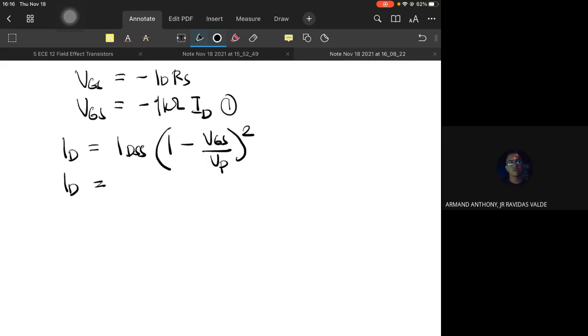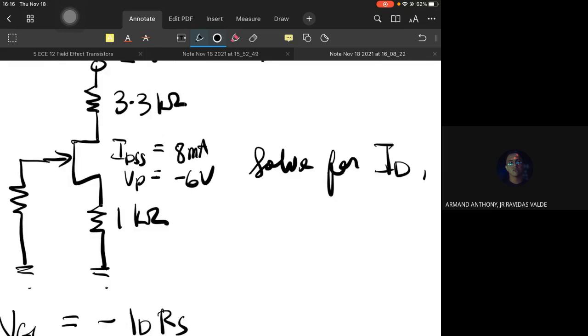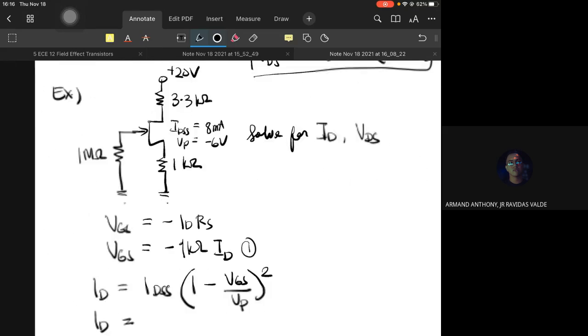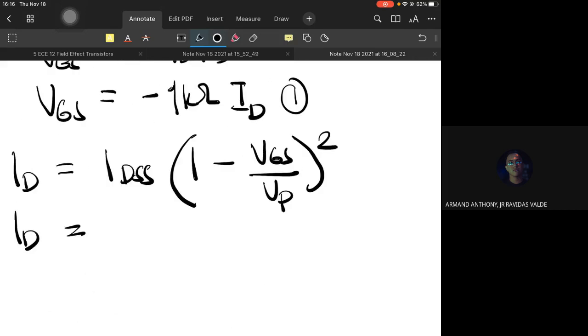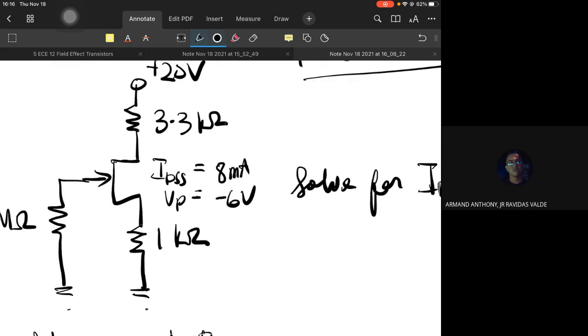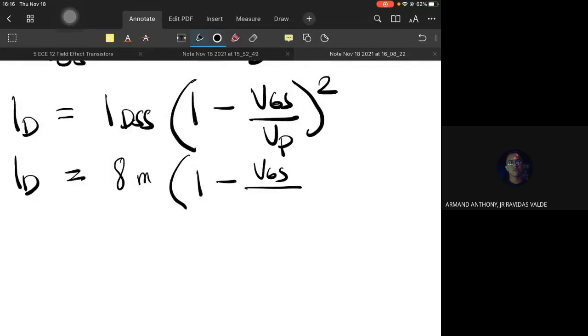What's IDSS? Given 8 milliamperes. 8 milli times 1 minus VGS over VP, where VP is negative 6, squared.